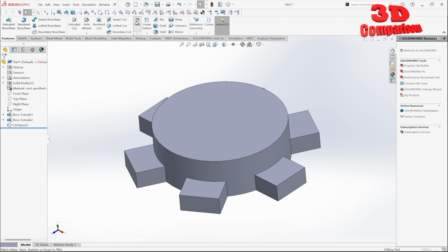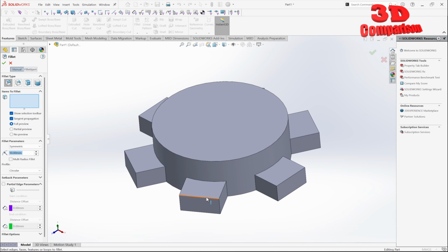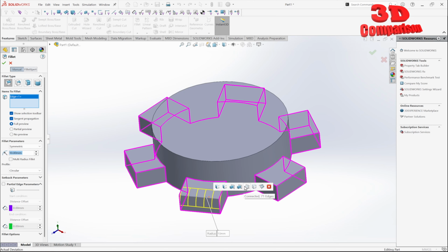And this is something that, as I said previously, SolidWorks has already implemented. If I just start a simple fillet, the same functionality, I select an edge and I receive over here a wide range of possible edges that I would maybe want to fillet. We have this one connected to start faces; in this case it will be 3 edges, and those will be highlighted. Connected to end, again 3, so this will be the other side. Internal to feature, as you can see, selects all of those. Then right features, connected, all edges, or over here, all convex edges.